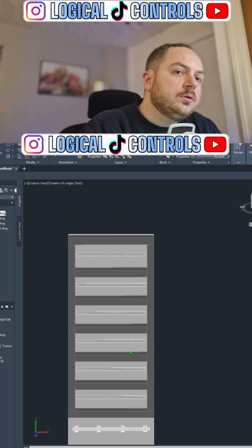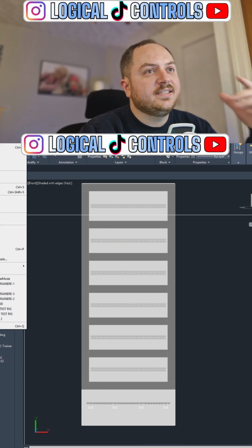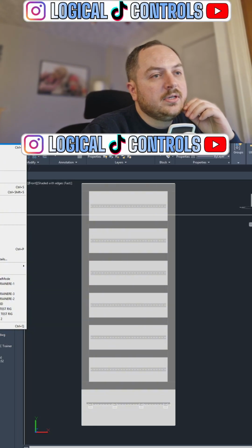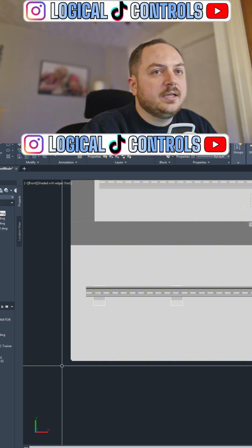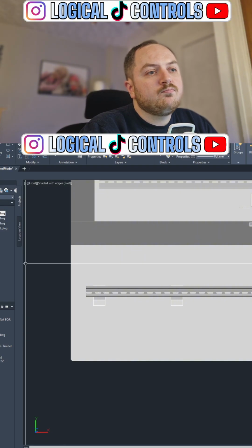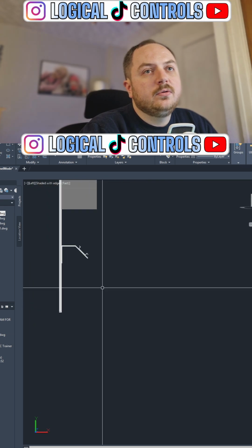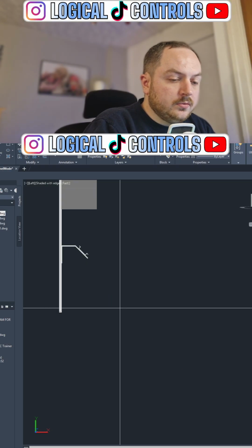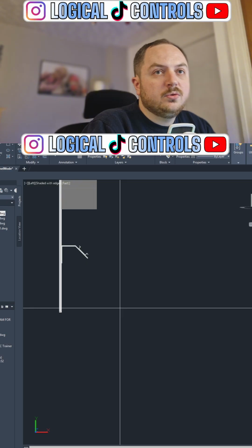Okay, so let's start chucking some components on. I'm going to start this time with some protection. No copper bar in the bottom for shielded cables. I haven't shown an earth bar. I guess let's do it. If you're saying it, let's just do it. So earth bar, I'll go into left view. Earth bar doesn't really ever have to be very big, so let's do, this is probably overkill, 5mm wide by 25mm high.